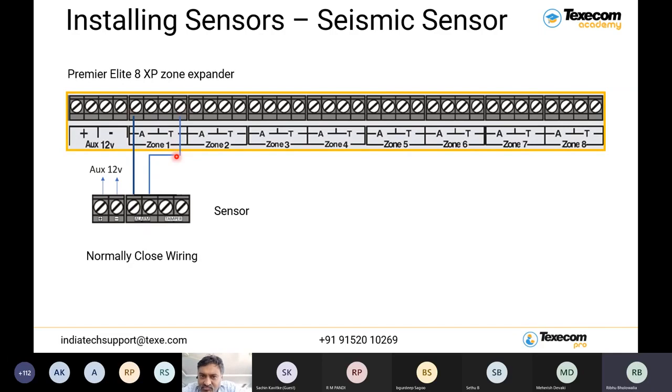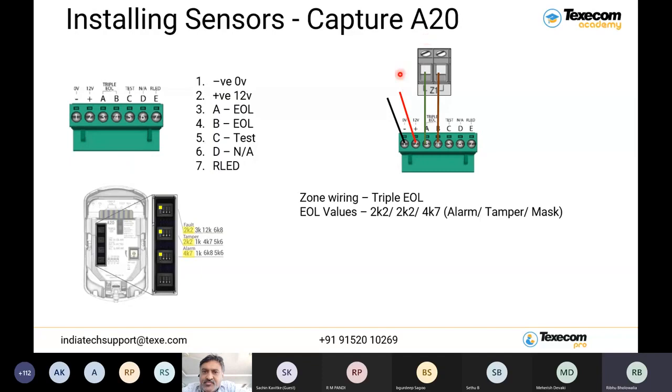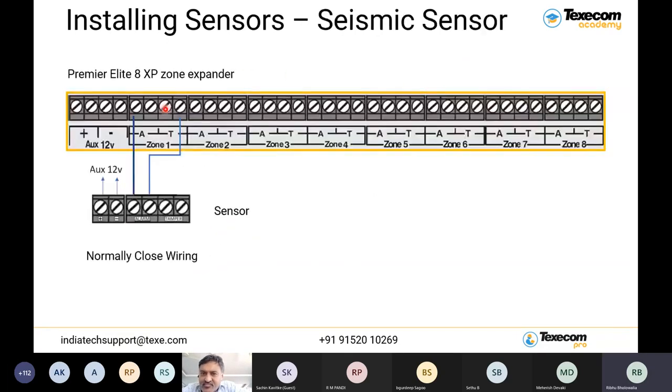Now guys, if you see in the last slide where I am connecting the PIR motion sensor, it was representing only a two terminal zone, right? But here it is representing four terminal zones, because the PIR motion sensor which we are connecting is connected on the control panel zone. In the LE24 control panel, all zones are having two terminals.